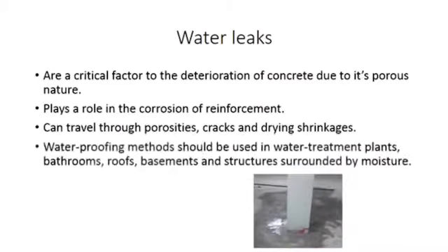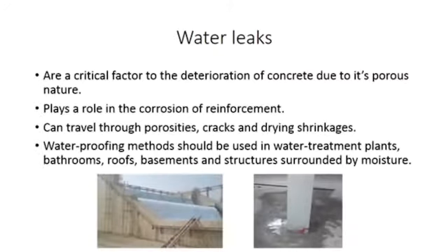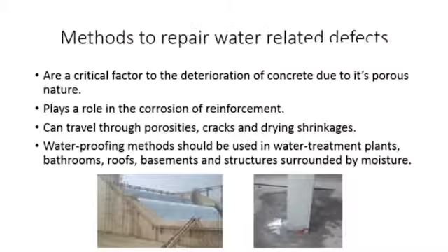Water can flow through porosities and cracks in the concrete and can travel through gaps formed from drying shrinkages. Waterproofing methods should be used in projects associated with water, for example, water treatment plants, bathrooms, roofs, basements, and structures surrounded by water.